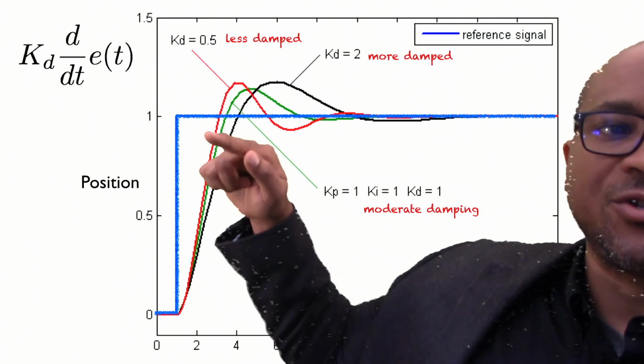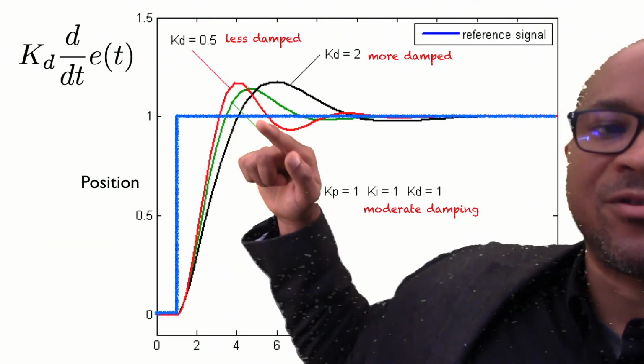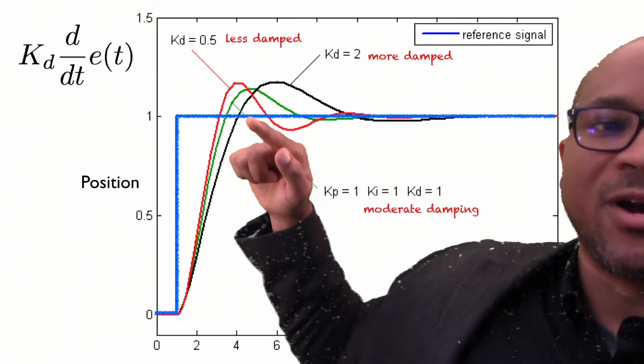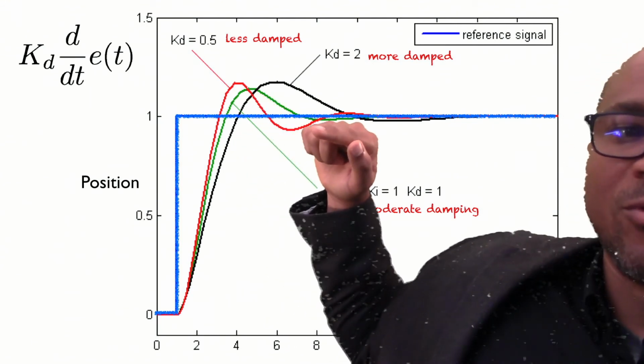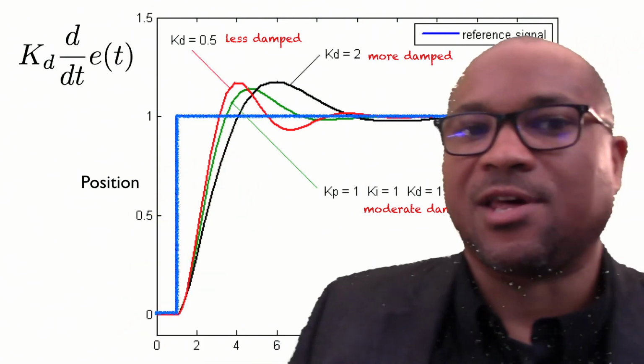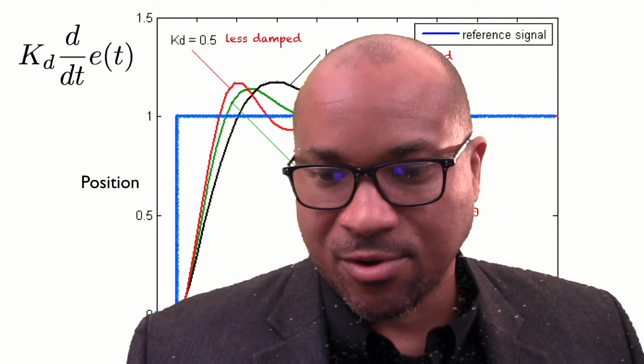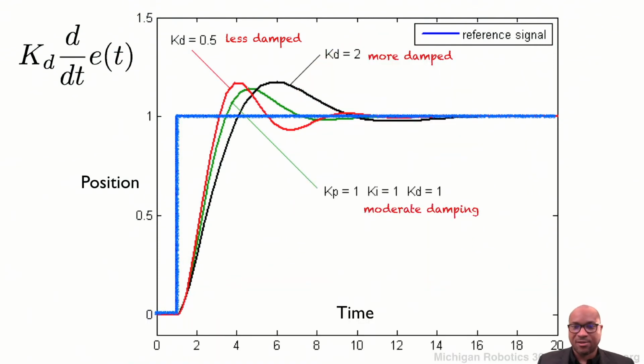We can overshoot and then start to have oscillations again. So we overshoot in one direction and then overshoot again, and eventually we'll get back to the set point, but it just may take some time. So we'd like to have a system that provides better damping than that, and so we want to tune in that direction.